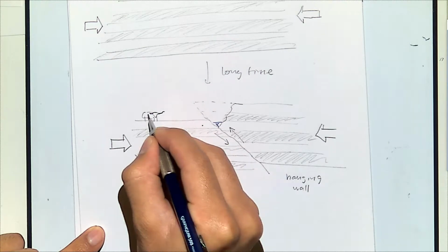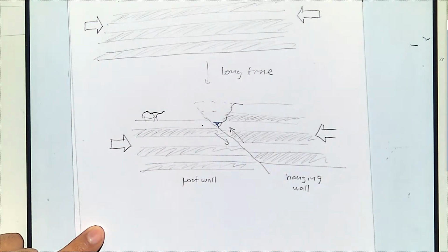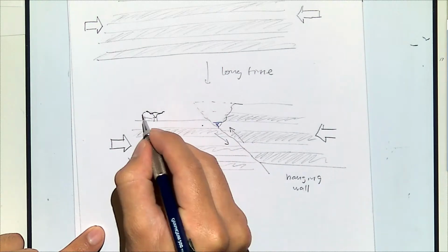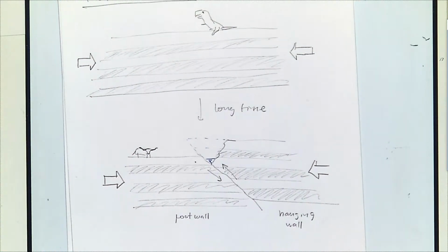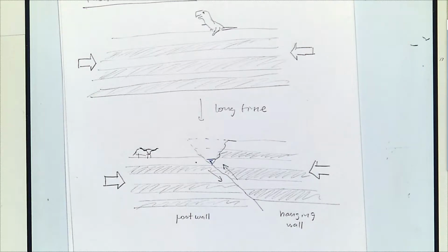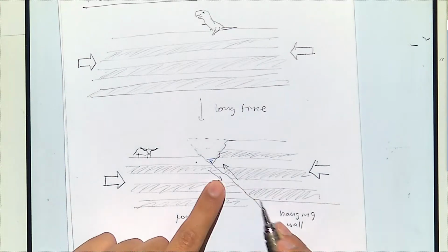And we are going to study how those faults form and what are the stresses required for them to form. So a fault is simply a shear failure at a large scale. And something very important is that because it is shear failure, notice that there is a displacement of the rock along the fault plane.